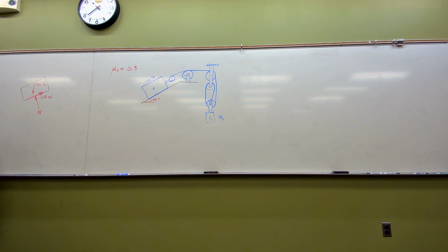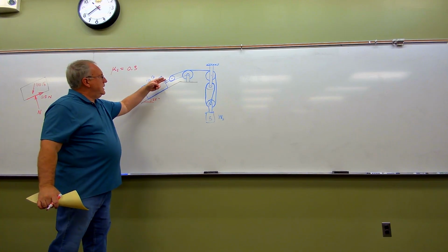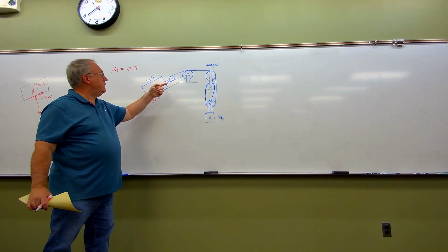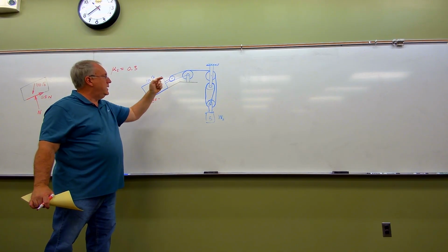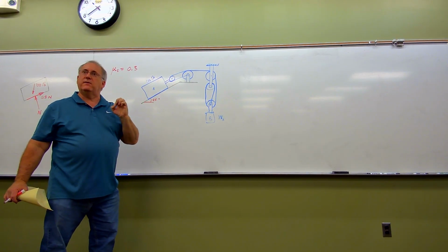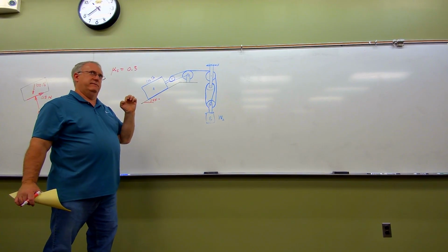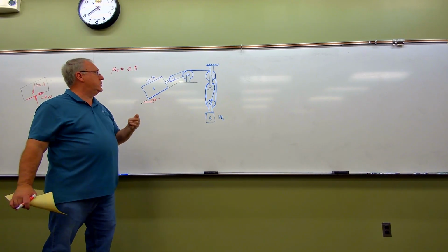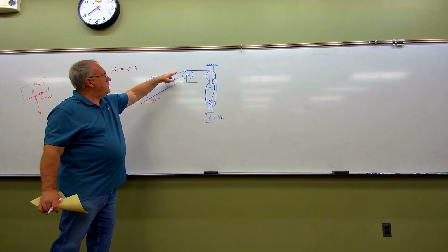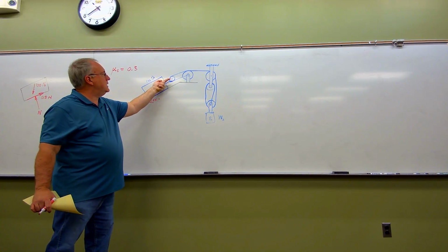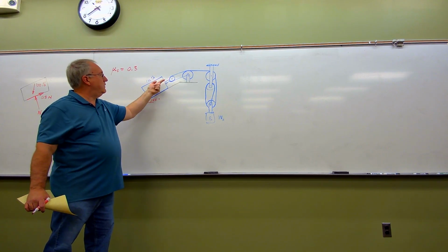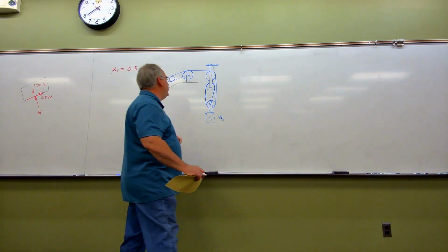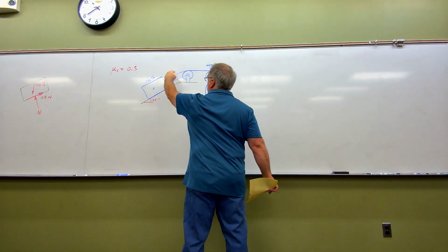And then we've got to think about the force associated with this pulley right here. If we think about the directionality of the pulleys, I'm going to ask you to take a little bit of a leap of faith, and we can resolve this if we need to through another free body diagram. But whatever these forces are right here, it's going to be represented, or could be represented, as a single force pointing away from this plane of contact right here. And if you're not sure of that, just imagine in your mind doing a free body diagram of the pulley.